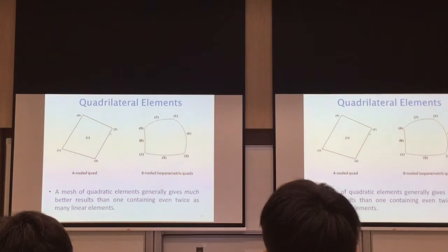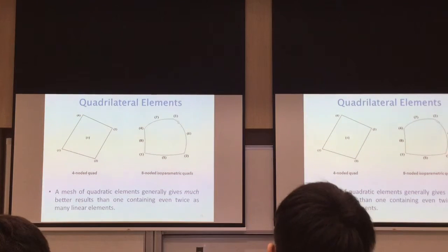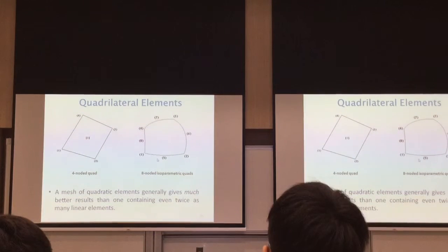With linear, your shape function or your displacement function is simply linear, while if you're going to use this one, your displacement function will include x squared or even higher. This one is simply x and y, while this one is x squared, y squared, and so forth. We have done that already, especially this morning where I gave you a displacement function or a shape function, so you will be able to have a feeling on what to expect from this quadratic element.